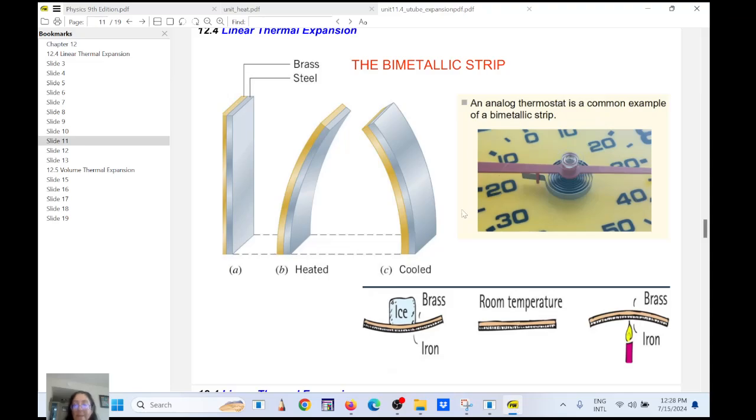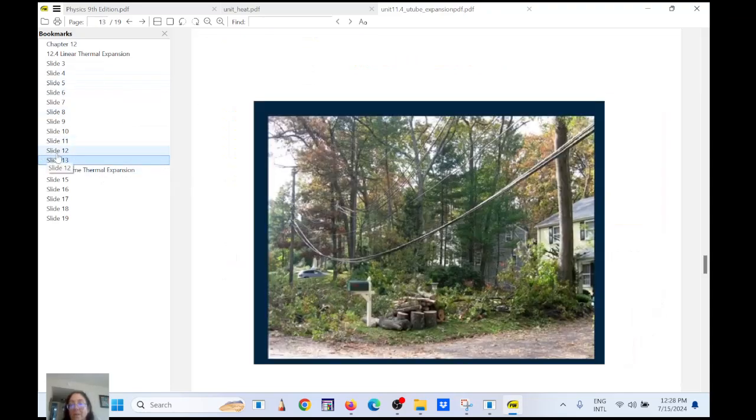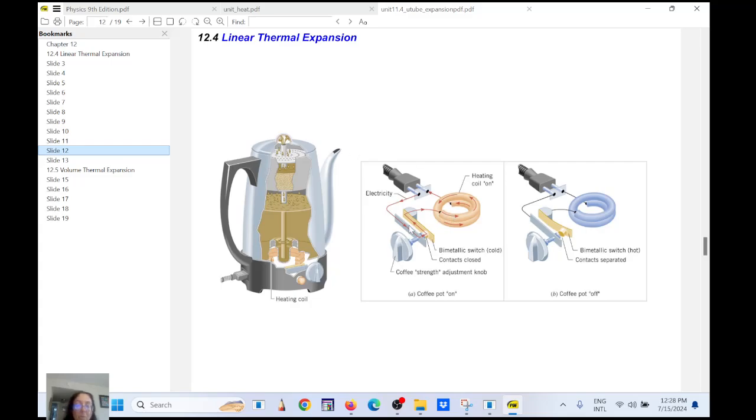And then, okay, we talked about that. So one very famous application is for switches, right? You see electricity here is flowing, going through one strip, going through the other. No, it's not a strip here, it's just a conductor. Then this is the strip here. When it gets hot, it will bend in this direction. When it reaches the high temperature, it will bend in this direction, so it will open the switch and the machine stops working. So it's a nice application.